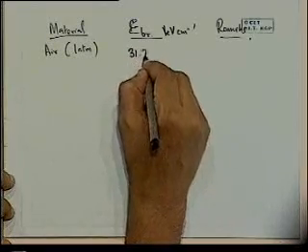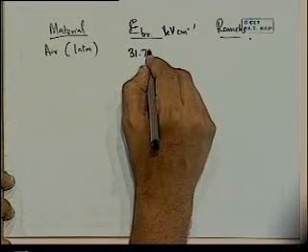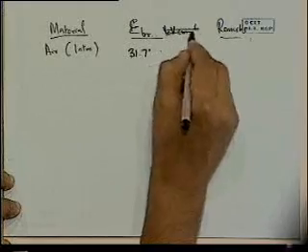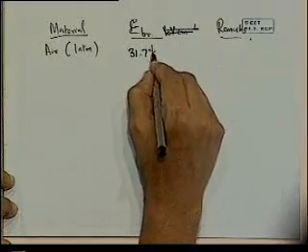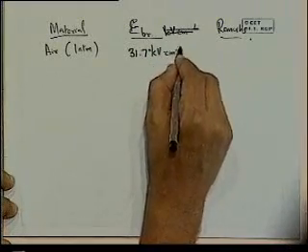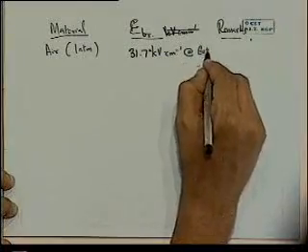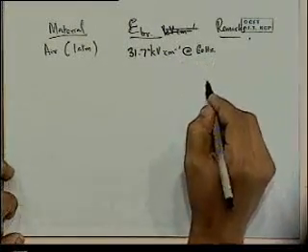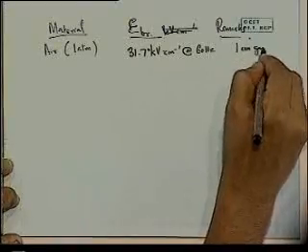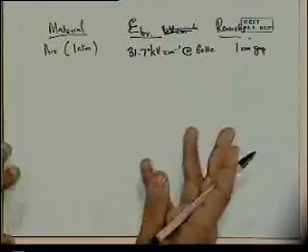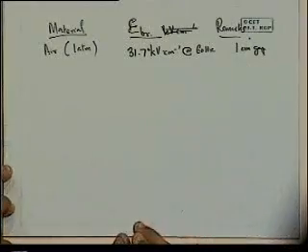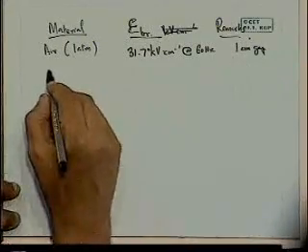It's 31.7. I should be careful, there's some that are megavolts also. All right, I'll write the unit separately. 31.7 kilovolts per centimeter, and the frequency is specified as 60 hertz. And this is discharge across a 1 centimeter gap. Already you have to give some conditions. If you try to reproduce it, it may be different in other cases.